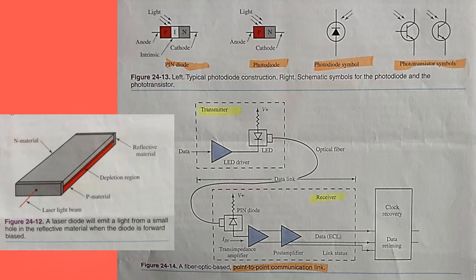The transmitter and receiver are first calibrated for the type of cables being tested. The core diameter and core construction vary among manufacturers. A short sample of the cable or jumper is used as a reference. Once the receiver has been calibrated to the reference cable, testing of the system can begin. For that, look at figure 24-15.